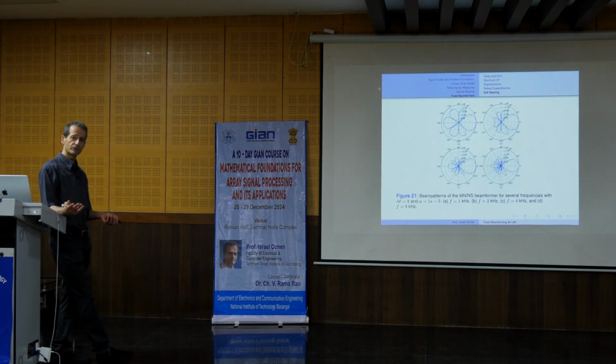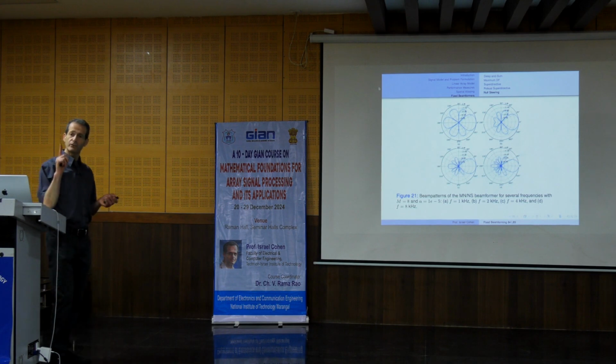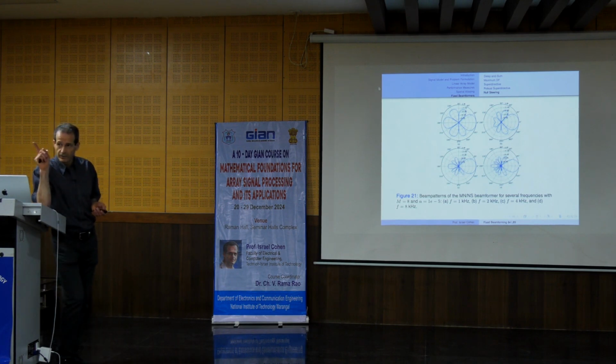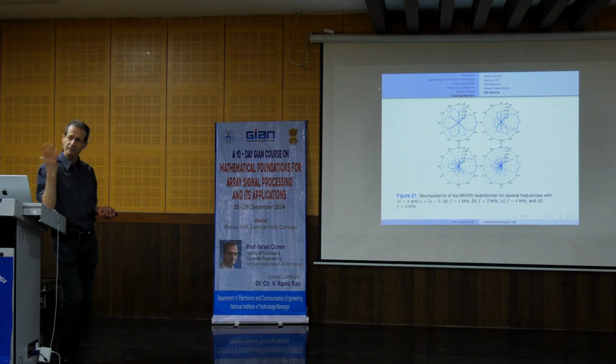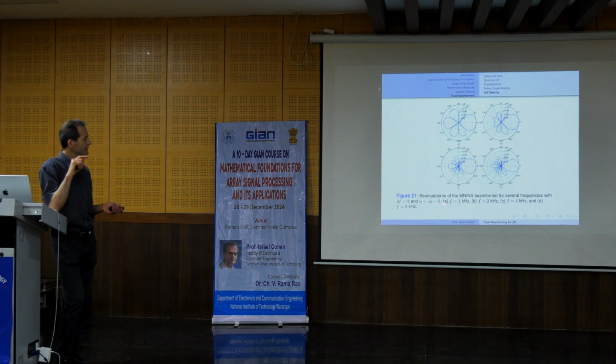When we increase the frequency, usually if we don't have aliasing, what happens to the directivity factor? Increases. Okay? Because we have a more narrow main beam. So the directivity increases if we don't have aliasing. If we have aliasing, we will start to see some side lobes increase, so the directivity factor will decrease. Now, this is for small alpha.